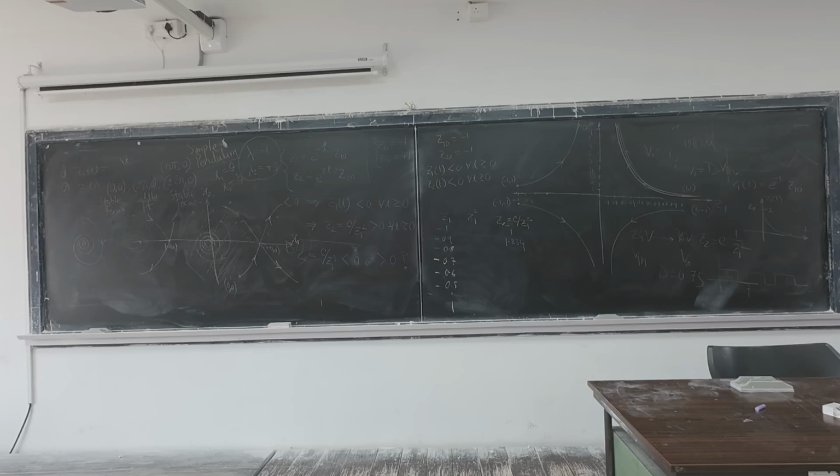So individually, those two configurations for switch on and switch off are asymptotically stable. If our system is asymptotically stable, without a forcing function or external influence it cannot change its equilibrium point. Here we are purposefully doing that because this operation is required, sometimes on and sometimes off, so that ultimately there will be an averaging.